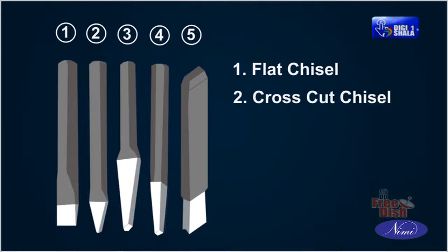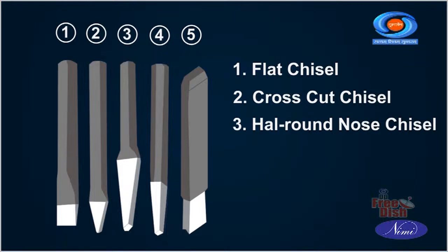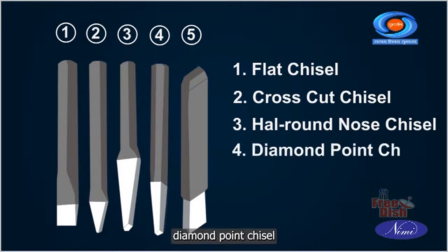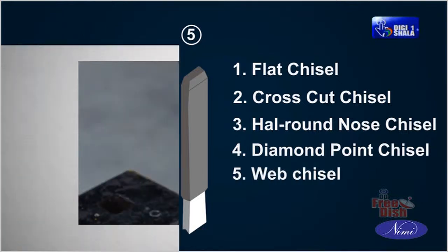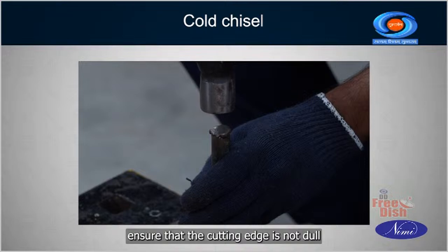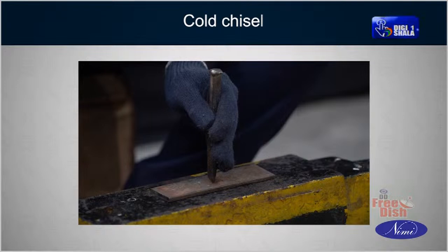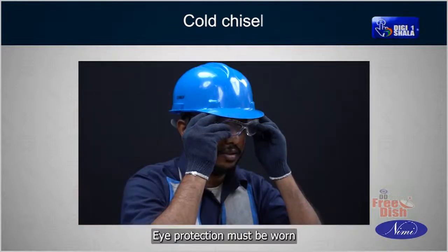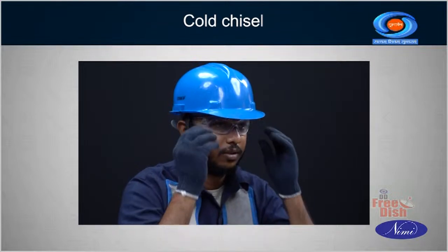cross-cut chisel, half-round nose chisel, diamond point chisel, web chisel. Before using a chisel, ensure that the cutting edge is not dull or chipped. Eye protection must be worn when using any chisel.